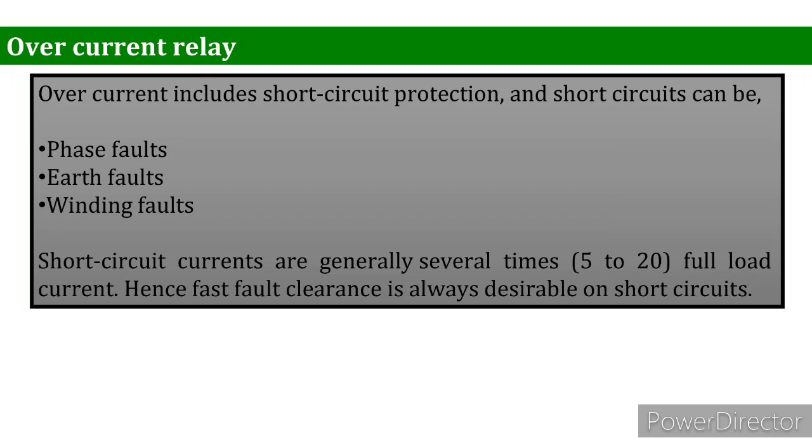The overcurrent relays give protection against phase faults, earth faults, and winding faults. Well, short circuit currents are generally several times, 5 to 20 times, the full load current. Hence, fast fault clearance is always desirable on short circuits to avoid maximum damage.